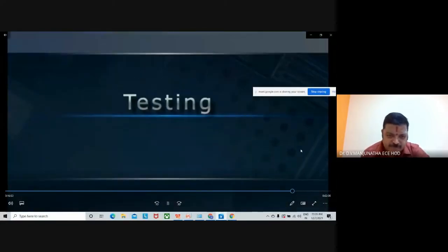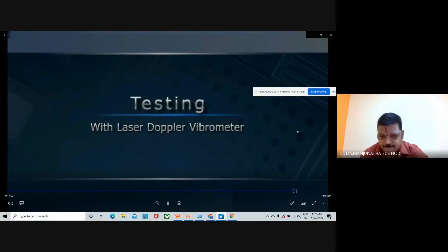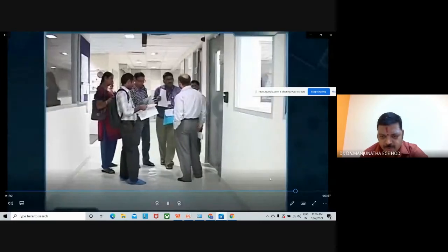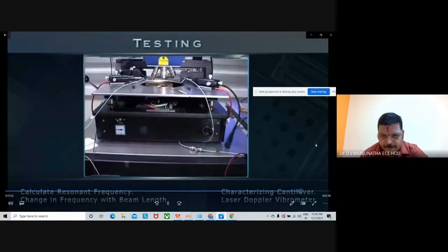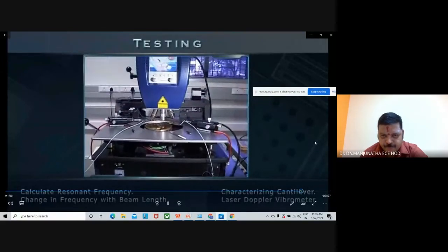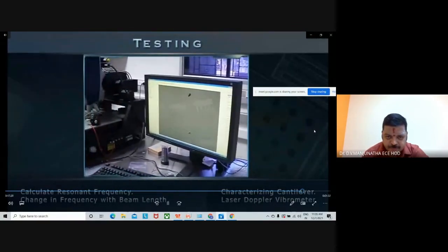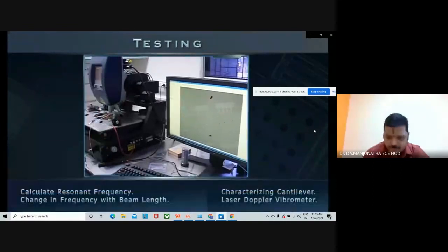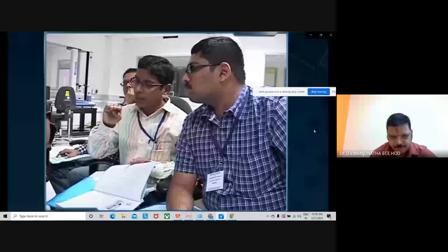So the final performance testing can be done by characterization. We are now at the Doppler vibrometer to verify that cantilever beams have indeed been released and therefore are functional. The laser vibrometer has a source of variable AC voltage that is applied across the sample's top and bottom silicon layers.